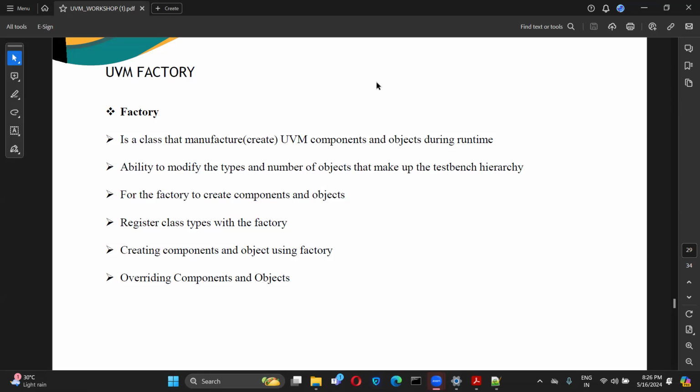When test is created, inside that we have ENV. We don't have ENV with test inside it; we have the test, and inside that the ENV. The way our architecture is designed, the UVM methodology should also work the same way, right? Then only it makes sense. If you create my driver first, it doesn't work, so that's why it is top to down and it will not work bottom to top.